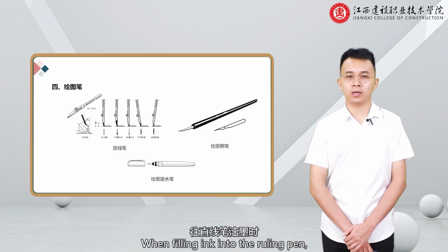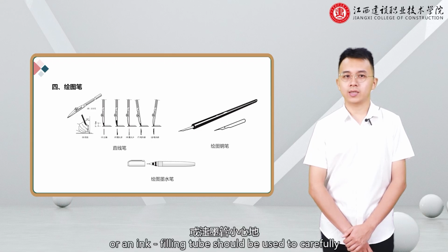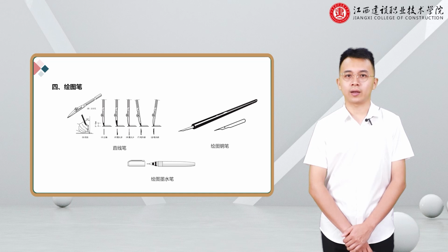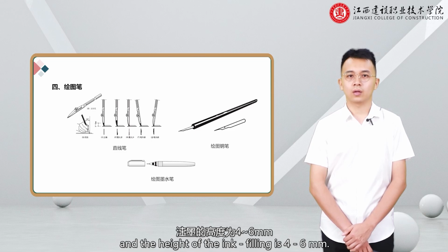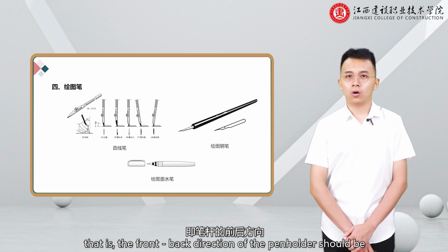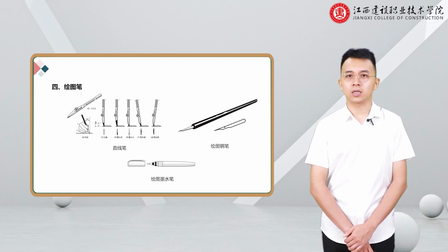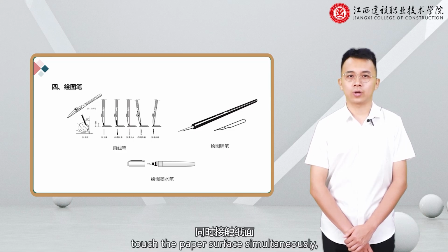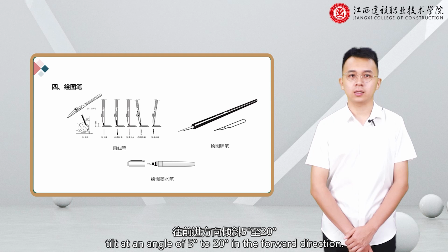When filling ink into the ruling pen, a drawing fountain pen or an ink filling tube should be used to carefully add ink into the middle of the two steel blades, and the height of the ink filling is 4 to 6 millimeters. When drawing lines, the ruling pen should be in the vertical plane. That is, the front-back direction of the pen holder should be kept at 90 degrees to the drawing paper, so that the two blades touch the paper surface simultaneously, and make the ruling pen tilt at an angle of 5 degrees to 20 degrees in the forward direction.